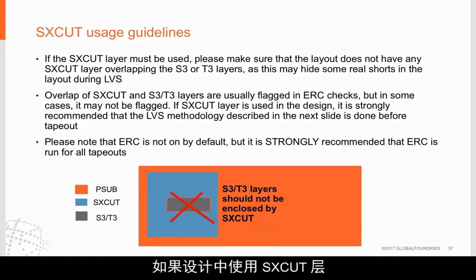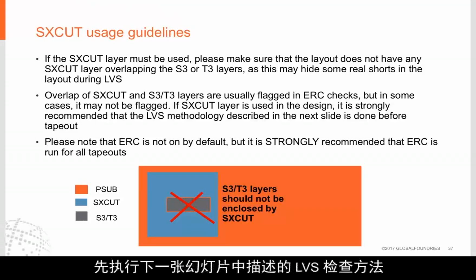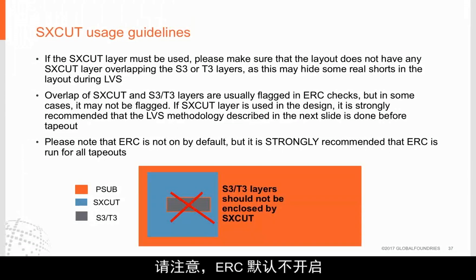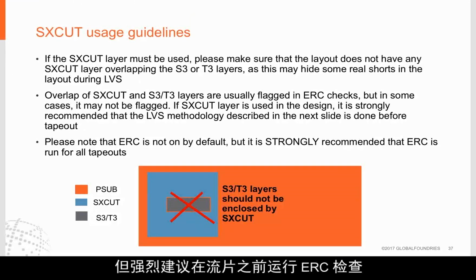If the SXCUT layer is used in the design, we strongly recommend that the LVS methodology described in the next slide be performed before tape out. And please note that ERC is not on by default, but we strongly recommend that you run ERC before taping out.